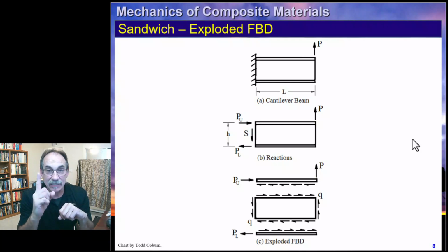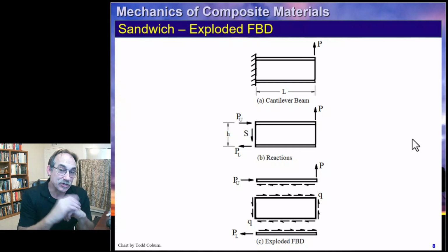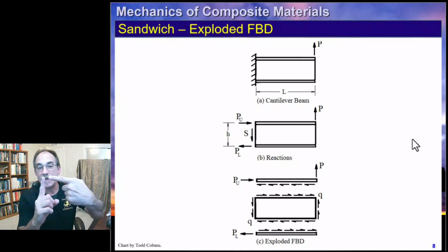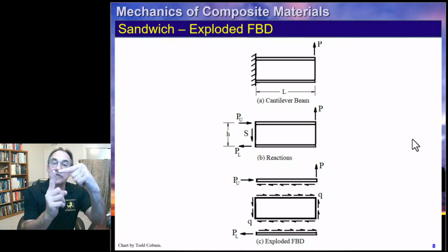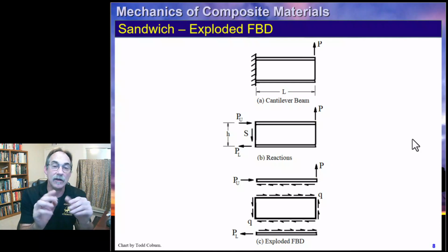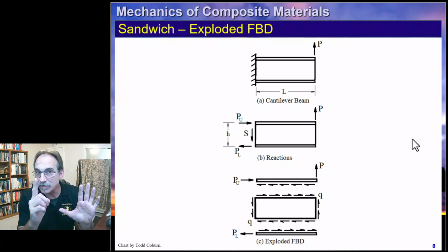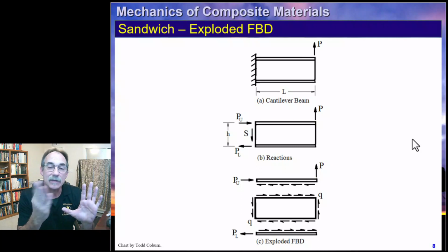And if that's acting upwards, remember, shear stresses are romantic little mothers. So if this one's going this way, then on the upper face, it's going to be mouth to mouth. Those 2 little arrowheads are mouth to mouth. And then if you look at the other end of it, the bottom end, the little toes of it, that's toe to toe with the other vector. Those cute little vectors are mouth to mouth here and toe to toe down here. So once we get one shear flow drawn, we can immediately draw all shear flows on the section.